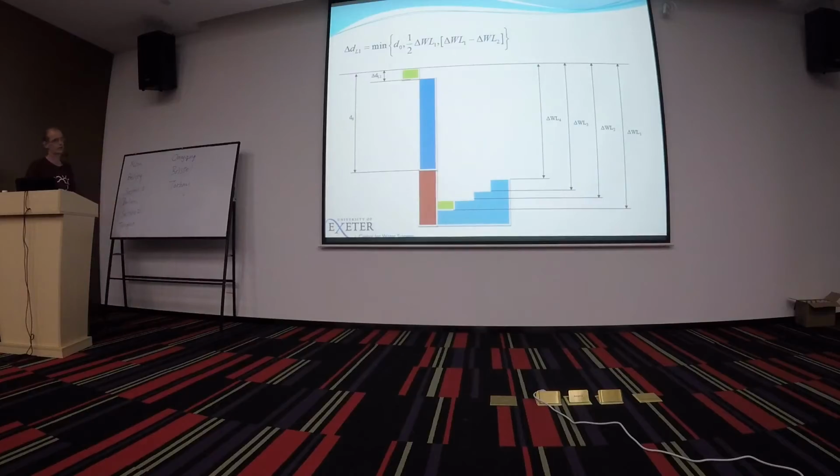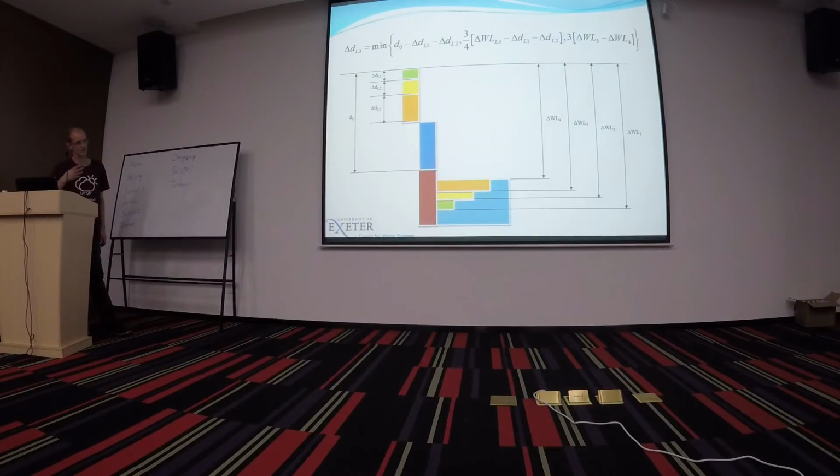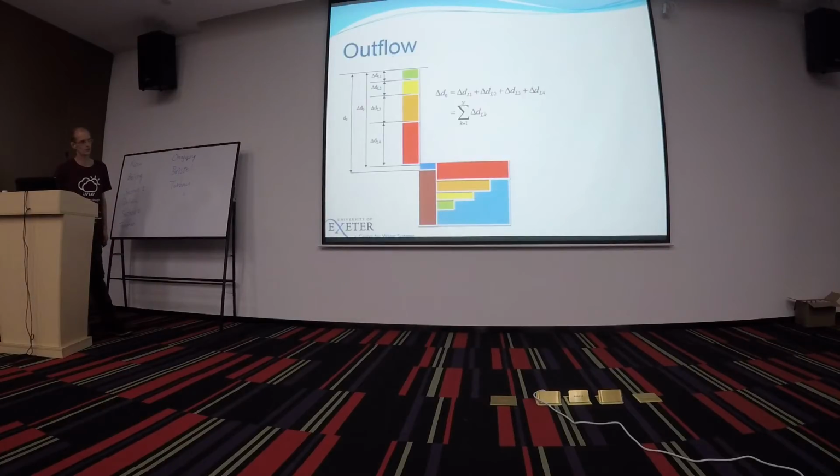So how that works is it takes the water in the main cell and then it starts distributing it to the lowest neighbor until that reaches the next neighbor. And then again, distributes some more of the water until it's filled up to the next neighbor, repeating the process along the ranking until it has distributed all of the water. And at that point, you know how much volume, so you can calculate how much flow is going into each neighboring cell.